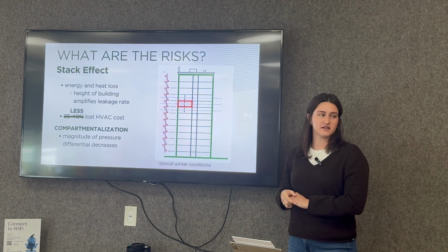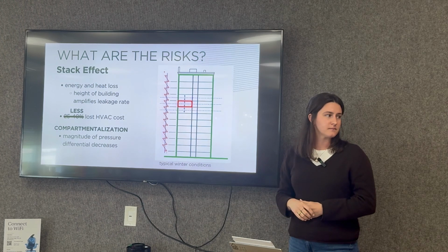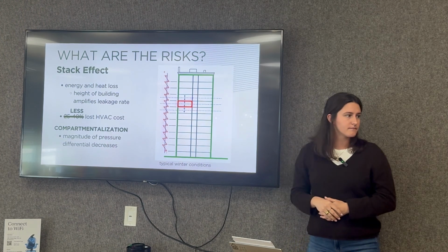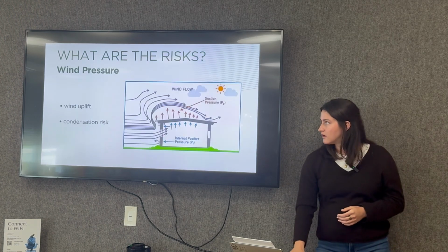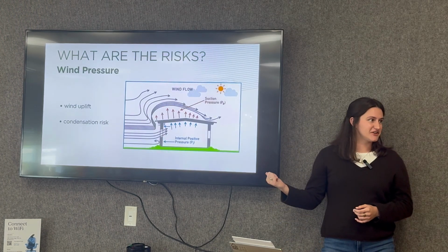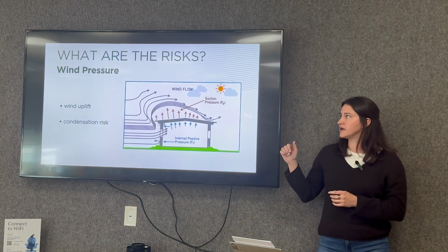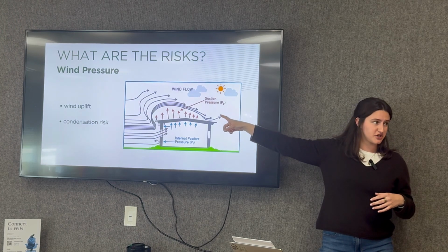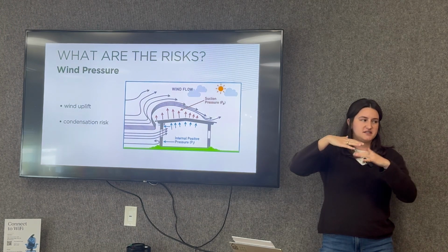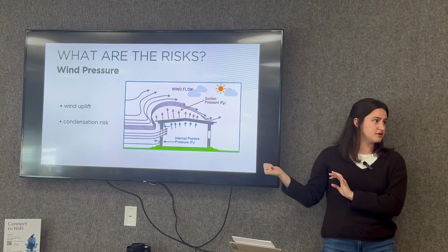Typically, yeah. So right, it's becoming more common. I don't know that I've ever had that taken into consideration in doing the uplift pressure calculations through ASCE 7 or FM. So wind uplift, thank you for the lead-in, is an entirely different thing. It wouldn't have any effect on it? No, because the wind uplift as it relates to uplift pressures is due to the air flowing across the roof, which makes this sort of suction pressure, whereas the interior compartmentalization is just the pressure inside of the building, which doesn't affect your values for uplift.